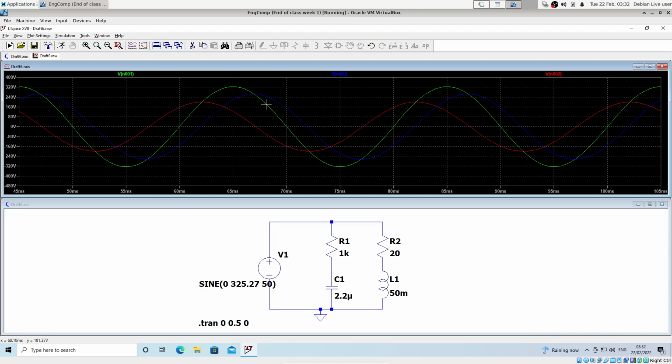So let's have a look at what the peak values are for the capacitor voltage. The capacitor voltage here was, if you look down in the bottom left hand corner in the status bar, when I hover over that node there, you can see that it's node 3. So V(N003). This is down in the bottom left corner of the screen. That is the one, if you look up here, which is being displayed with the blue waveform. So the blue waveform is my capacitor voltage.